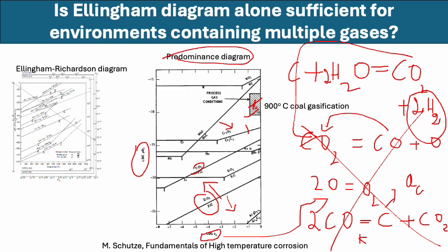But the Ellingham diagram is the simplest one, and we can have emergence condition diagrams for alloys, and for multiple gas containing environments we can have predominance diagrams. So you need to bear this in mind, and these are often used in the industry to determine what kind of process will happen, whether internal carburization has happened, because sometimes carburization is done on purpose, but most of the time we do not want these blocky carbides that can deteriorate the mechanical properties significantly.